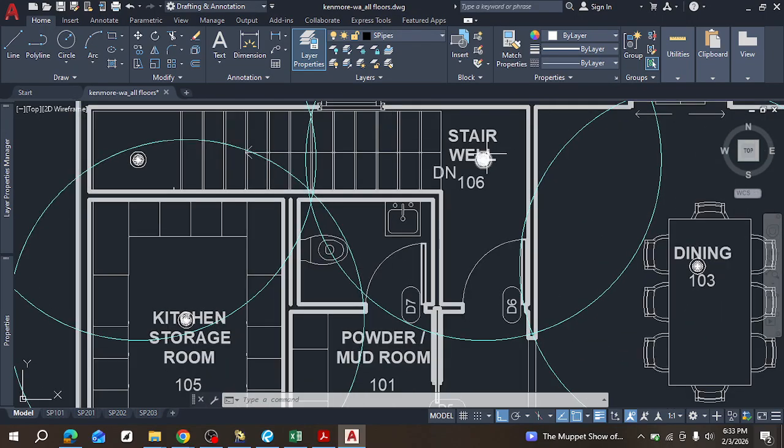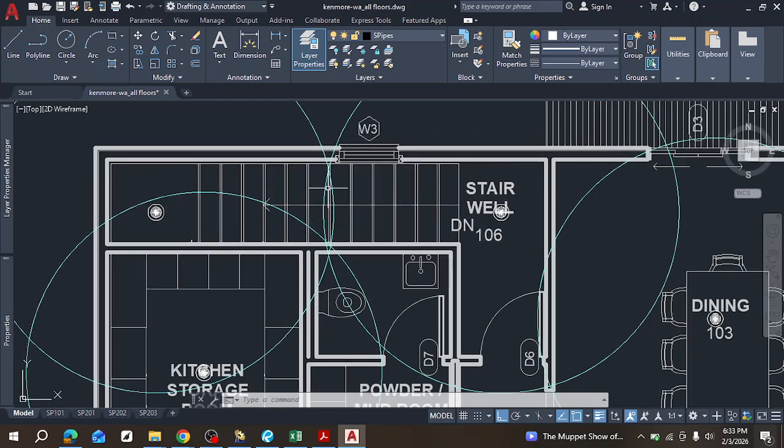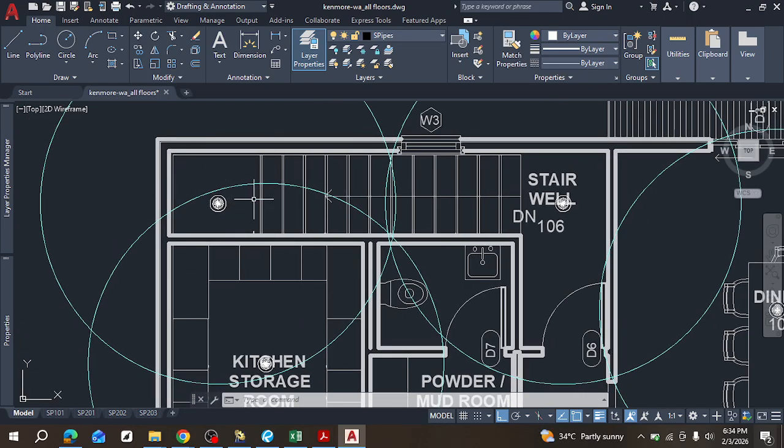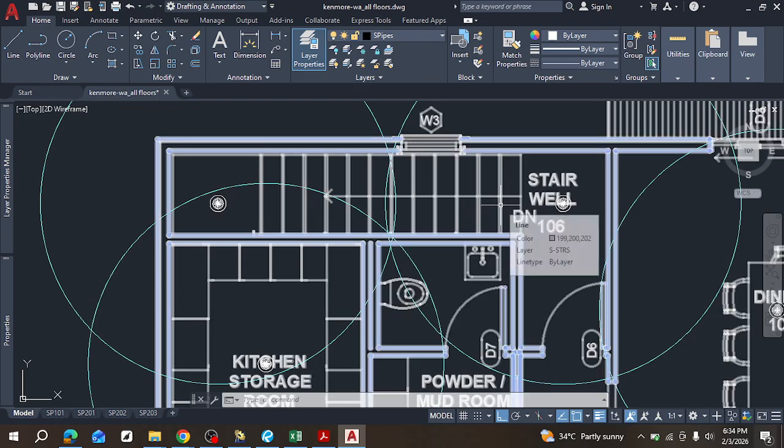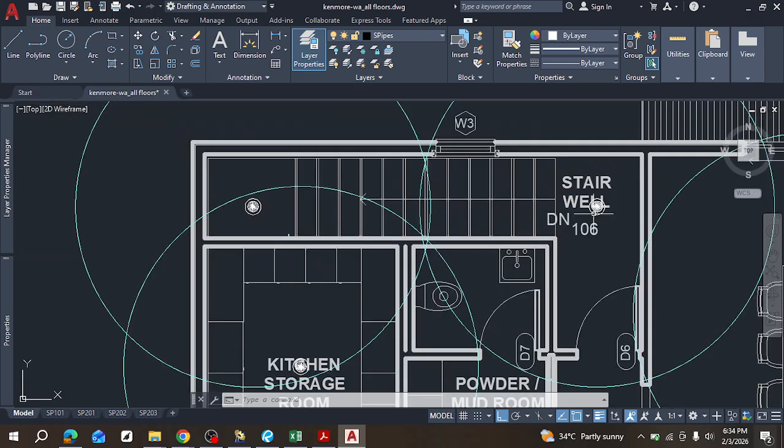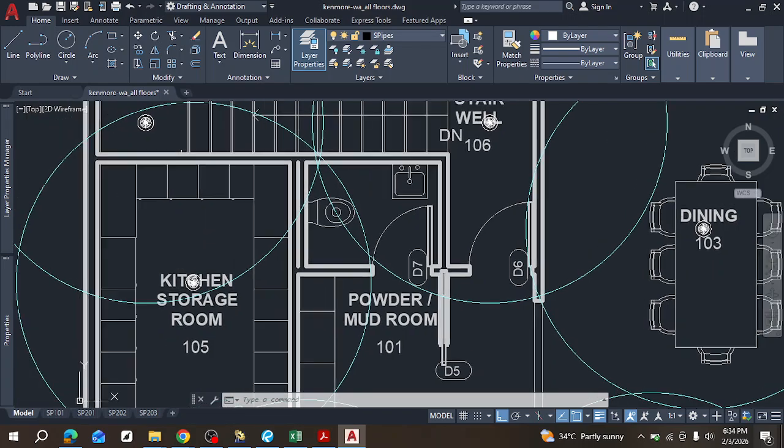And then at the end there's also a sprinkler because this one, you can see that the coverage doesn't get to this point. Putting sprinklers for a staircase area is a bit tricky because the floor is not exactly level. There's like a rising floor, right? But thankfully we have a ceiling area, the ceiling of this place, that's where we're installing this. So it's just going to cover over this cascading, sloping staircase, and this also covers. But we'll also look at another staircase.